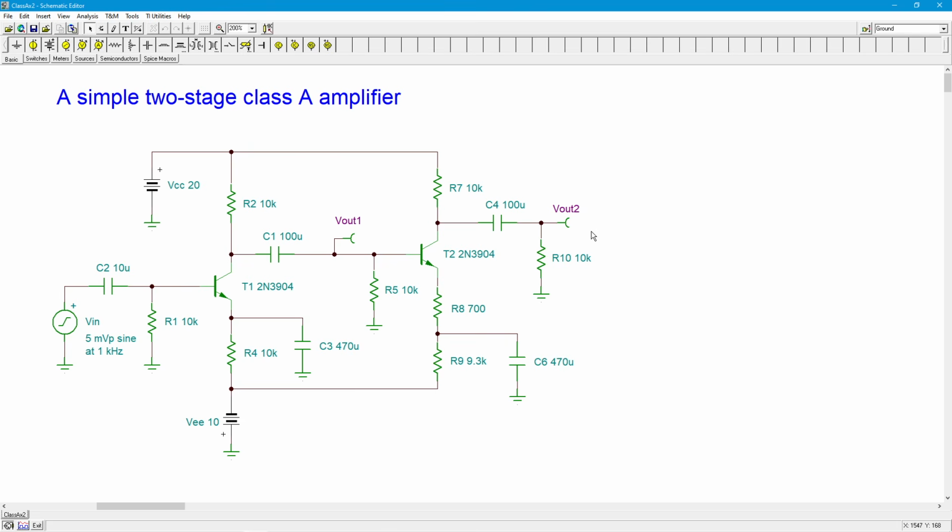Now, we already know that this is not a matter of frequency tailoring. It's not like these higher harmonics are being artificially reduced. We already looked at the bandwidth of this thing, and it went out to several hundred kilohertz. I'm only testing this with 1 kilohertz. So it's flat, way, way above what we're actually looking at as far as distortion harmonics. So that's not the issue.